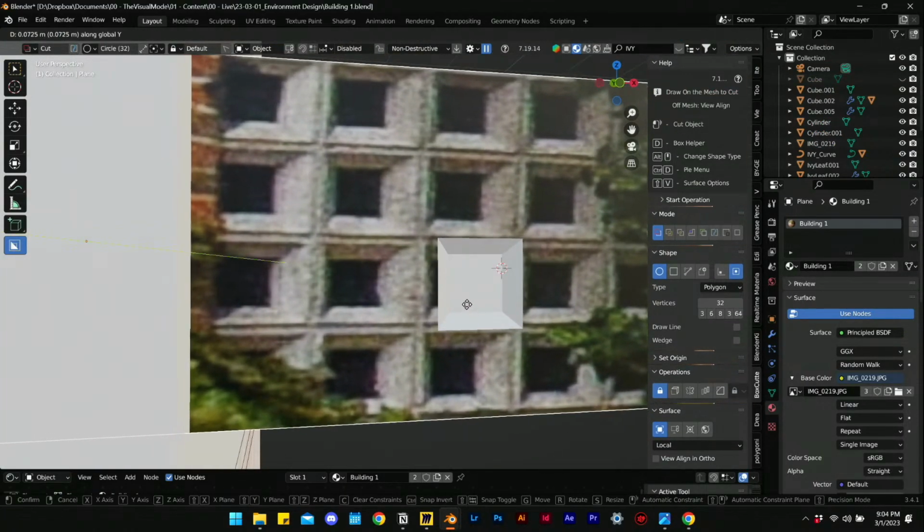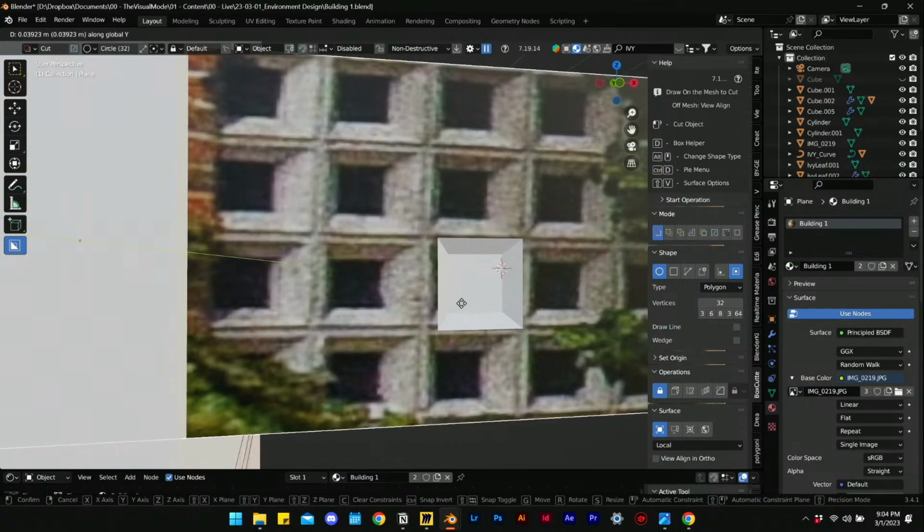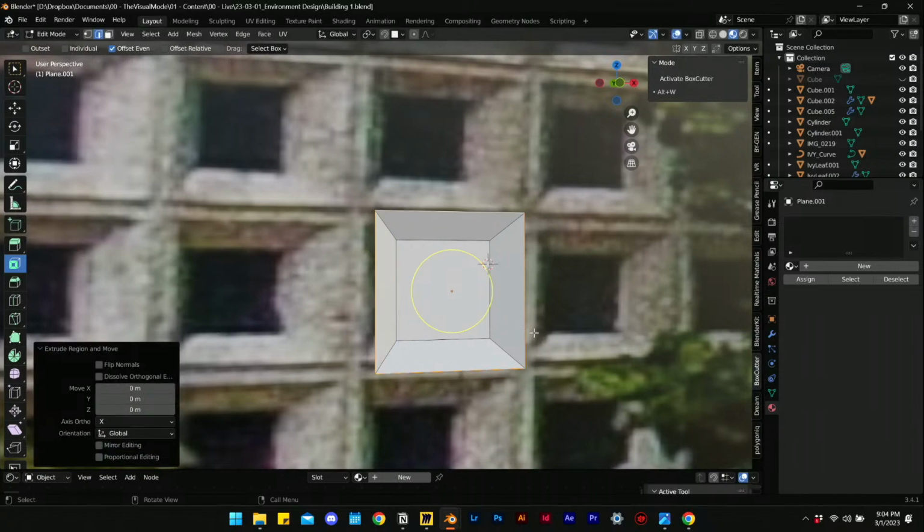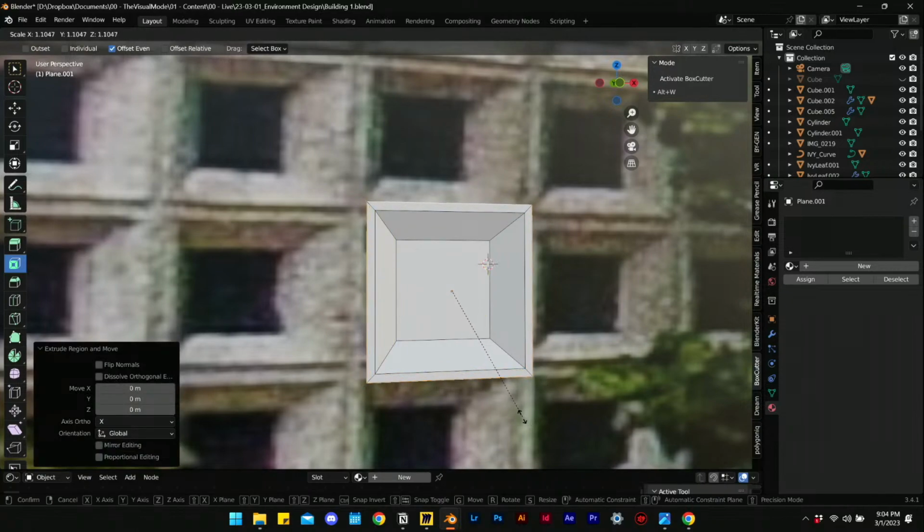move it further back a little bit. There's a little bit of a border here. So I'm just going to hit tab again with edge mode, alt click to select the boundary faces right here. And I can hit extrude, escape, so that they snap on, and then scale to just move it out like that a little bit.